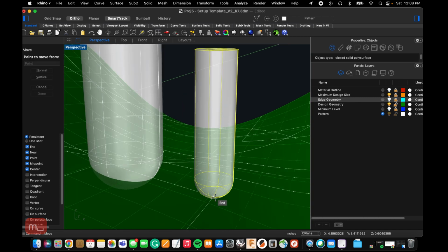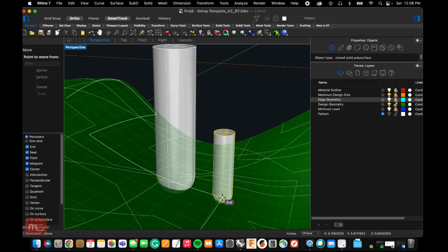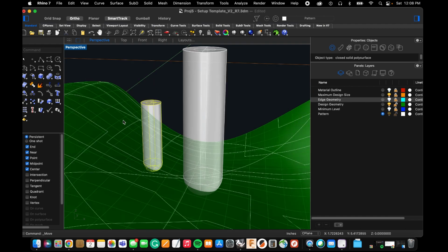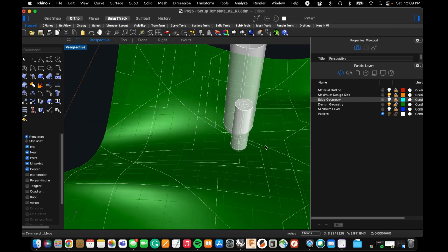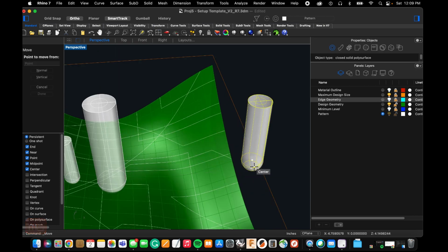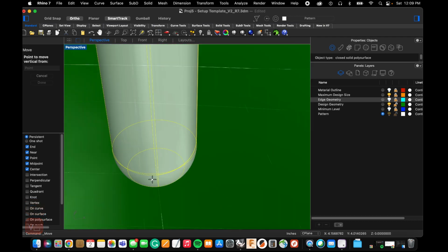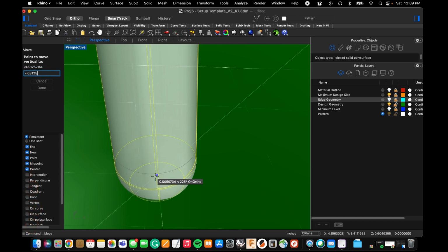The 1/4 inch will deviate or cut into vertical from there, negative 0.0625, 1/16 of an inch. Okay, and then we'll move kind of like that. And then the 1/8 inch, there, move vertical, negative 0.03125, or 1/32 of an inch.